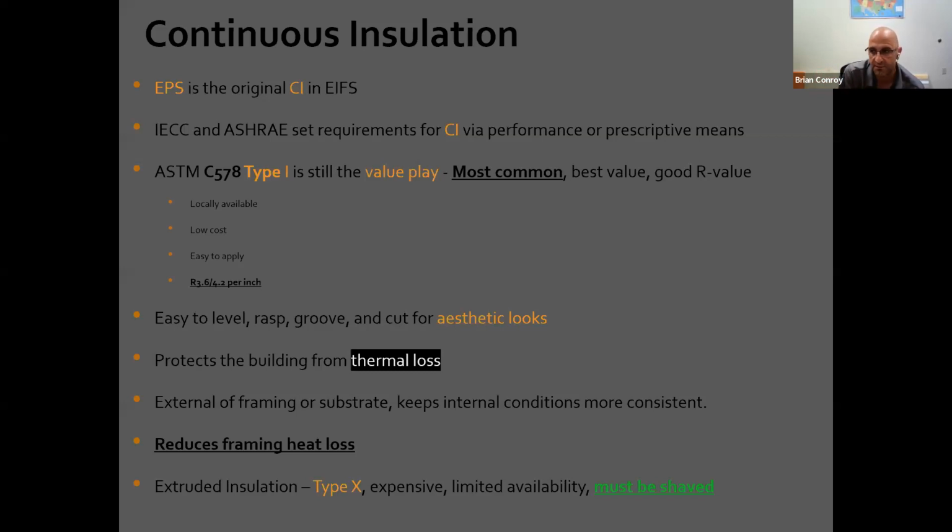Now, sometimes I have gotten to a point where that R value makes a big difference because they don't have an extra half inch of space that they can add, like a 2.5-inch EPS versus a 2-inch XPS. But that's very, very rare. So again, from an R value standpoint, I would say 4 for EPS, 5 for XPS, and kind of go from that way.